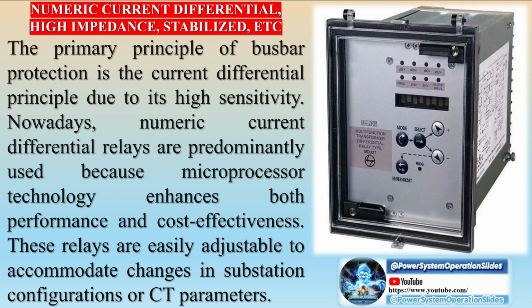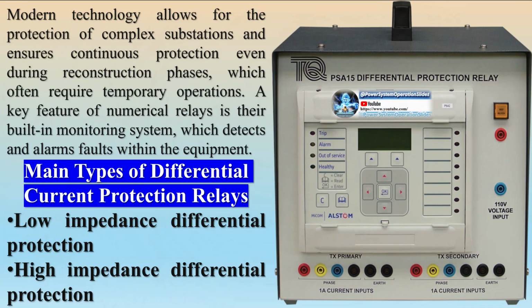The BFP operates based on the following principles. Confirmation of overcurrent: the main criterion for the operation of the BFP is the detection of an overcurrent through the circuit breaker. This ensures that the circuit breaker has indeed failed to operate. Circuit breaker position criteria: the position of the circuit breaker, open or closed, is also monitored to confirm whether a fault condition exists.